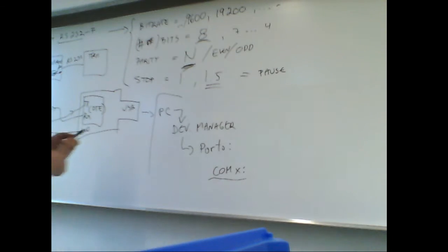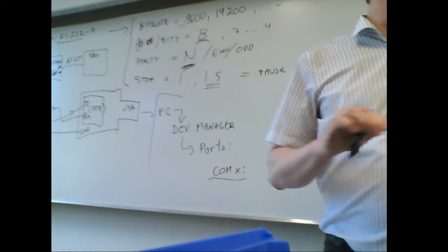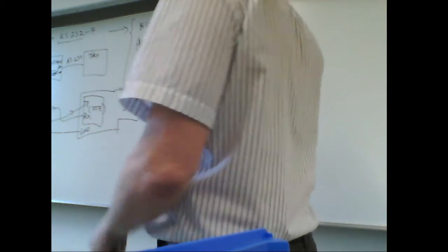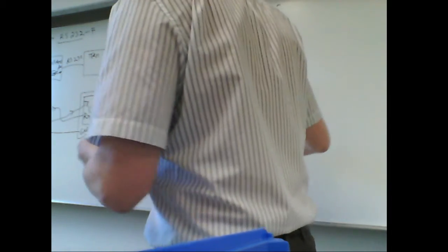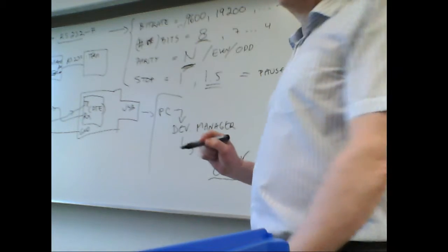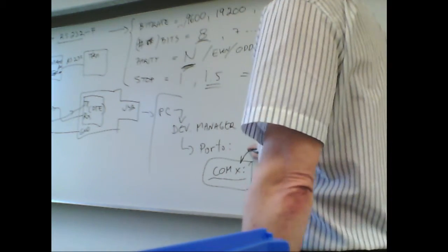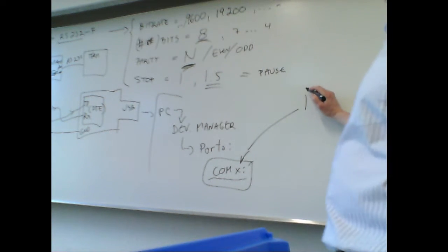Okay, so yeah, it's really ancient technology. So basically, when you plug this one in, it will show up as a COM port, and make a note of which COM port. Then you can take some terminal program.